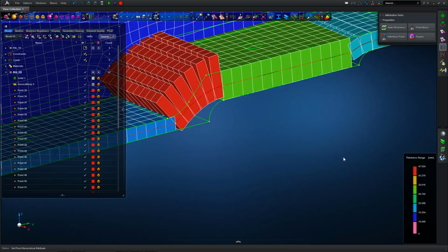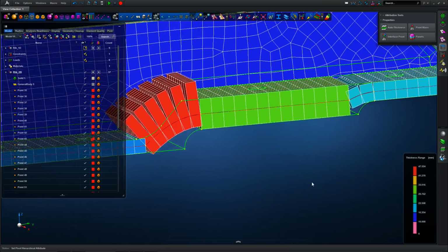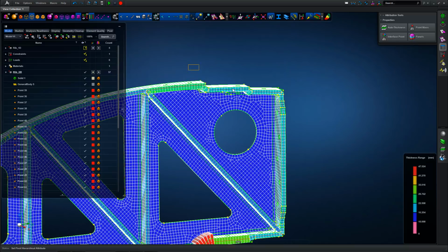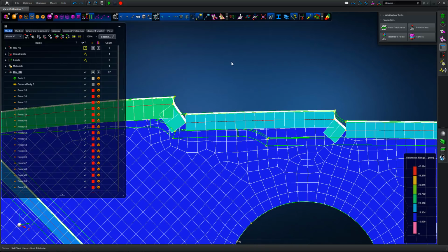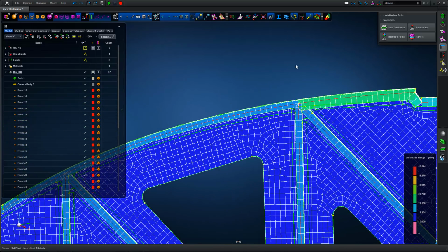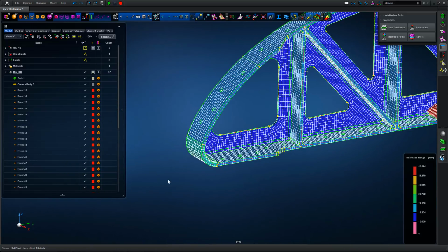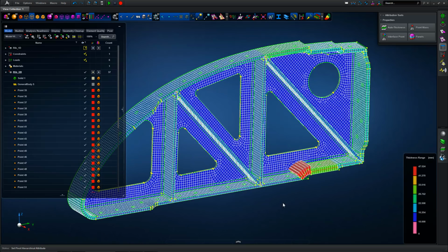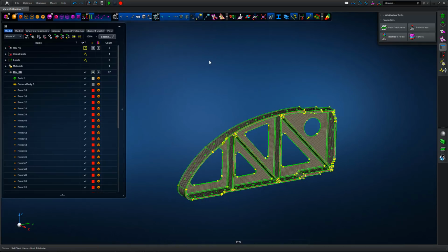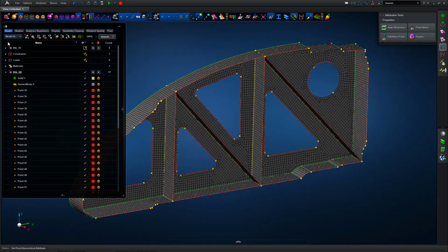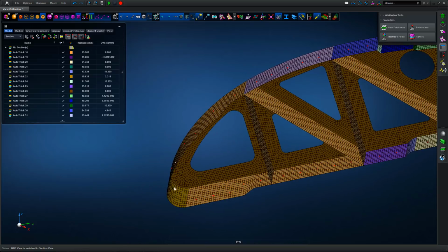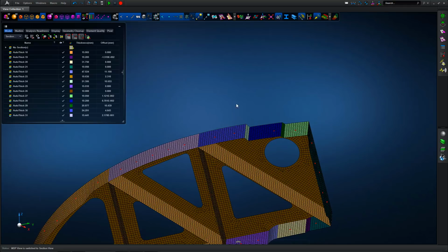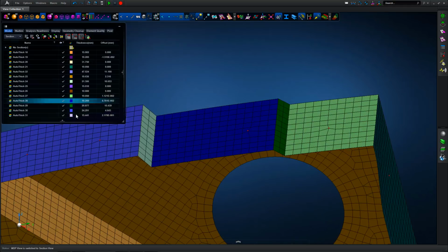And we can see, if we look at the joggle region down here, it's made a good attempt, but the joggle thickness has thrown a bit of a wobbler in terms of the local thickness attribution at these points. So once we've been through the model, we can go back into the section tools and update the thicknesses accordingly. And again, you can see at the nose of the rib there was a slight inconsistency between adjacent meshed regions. So going to section view, this then gives us sections on a color-coded basis.